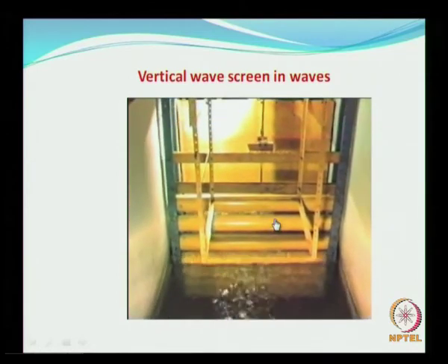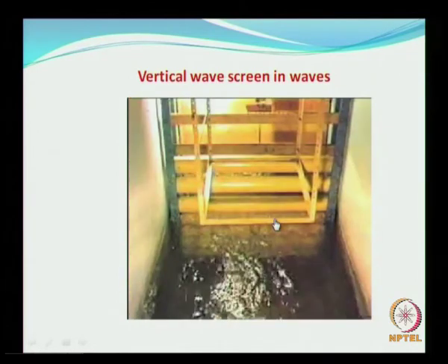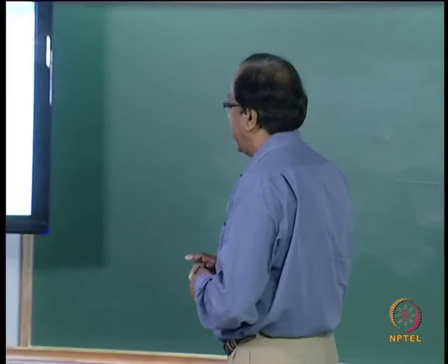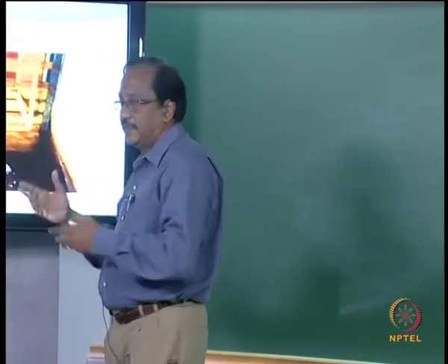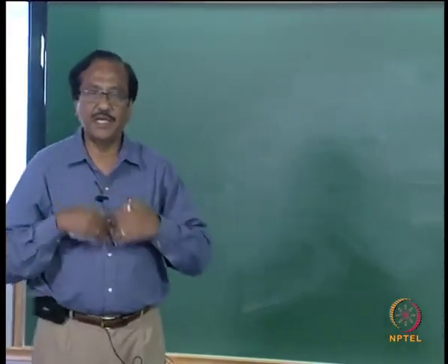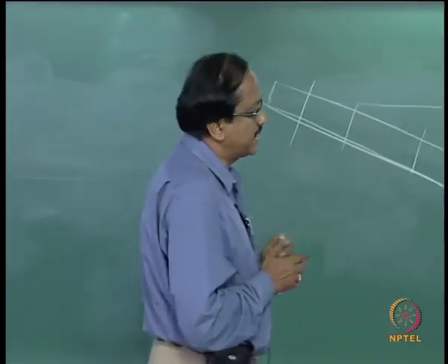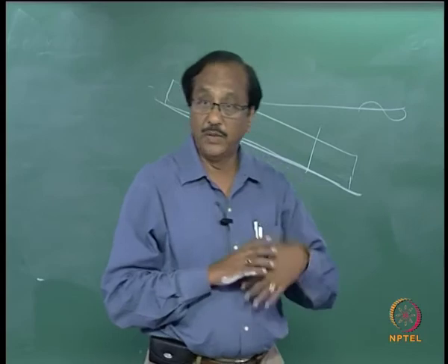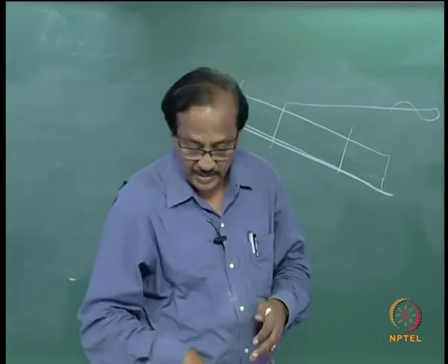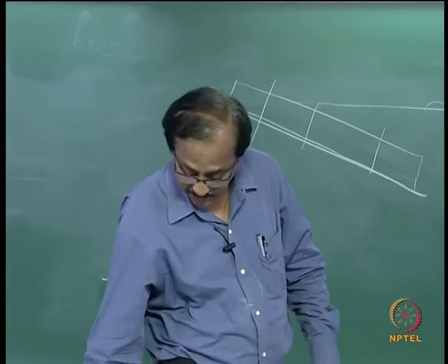So in order to reduce all these things, you have a porous structure in front of an existing structure or in front of a structure which is in distress, so that the wave screen can act as some kind of a relief structure for the original structure. So this is a kind of a study which has been carried out.